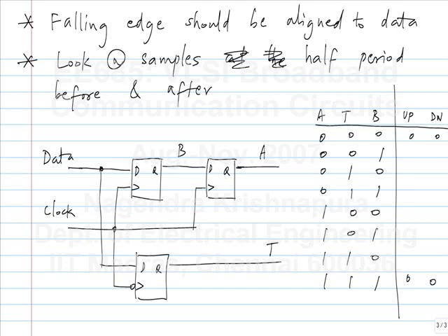How do you decide that? Basically, if you want to delay the output phase of the VCO, you have to reduce its frequency. Then the edges will start getting delayed, and it will reacquire alignment depending on the bandwidth of the VCO. Similarly, if you want to advance the phase of the VCO, you have to increase its frequency. So the successive edges will come closer and closer together. Finally, it will lock to the right thing. So in this case, if it is too early, you have to delay it. So down is 1, up is 0. And 1, 1, 0 is the same as 0, 0, 1. The exact polarity of the data doesn't matter to us.